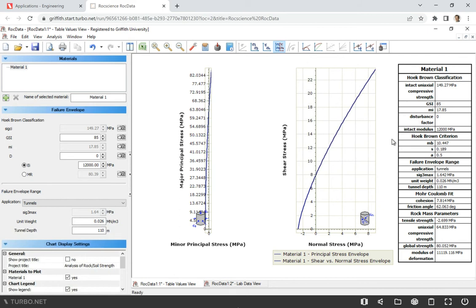So this is the data that we're going to get. So we still have this UCS. It didn't change, 149. But you will see that when we applied it to rock mass and we put here GSI 85, uniaxial compressive strength decreased to 64. So that will be the value. Tensile strength will be 2.699 MPa for the rock mass. And it's tensile strength, that's why it's negative. We have all these constants, s and a, sorry, alpha.